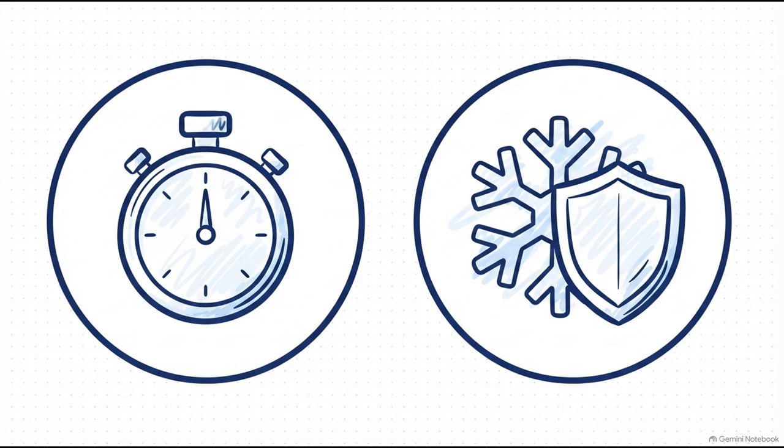But check out the cold weather rules here. If you're in cold weather, that rule changes entirely. Protection has to continue until the specified strength condition is definitively reached. Also, keep in mind that natural curing can only replace your specified curing methods if the relative humidity in contact with the shotcrete stays at or above 85%. And, this is key, the engineer actually authorizes it.